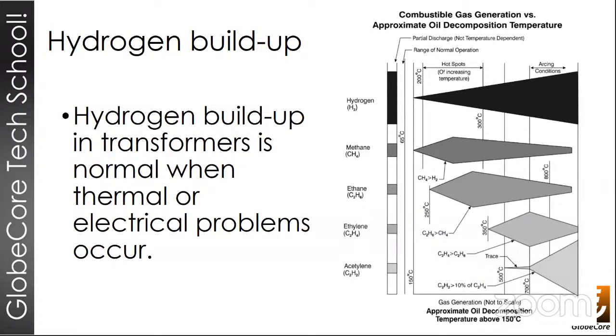Hydrogen is associated with low intensity problems, but as we can see in this graph in this slide, it actually is generated by all faults. So when studying faults of greater intensity, the characteristic gases are used, for the formation of which more energy is required, but still we will always register continuous buildup of hydrogen.